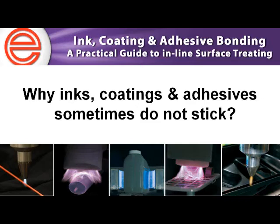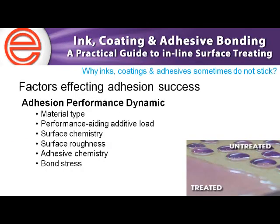So now we know a little bit about surface treating. Let's talk about why things sometimes don't stick to the product. There are various factors affecting the success of adhesion on your product. Some of the dynamics include material type. Different materials, say polyethylene, maybe polyester, PEEK, ABS, they're all going to have different characteristics and bondability as they are in their raw form.